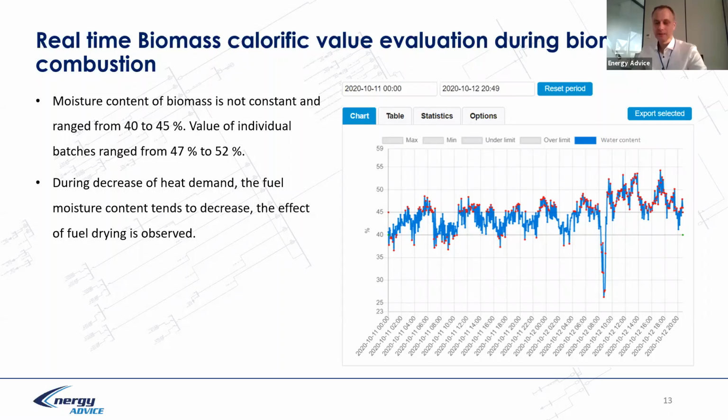Okay. Maybe you are asking me a question about the dew point of the flue gas inside the boiler. So the supply temperature, in fact, we cannot optimize somehow the supply temperature of the water to the boiler. We should keep the temperature in some range which is defined according to the dew point.